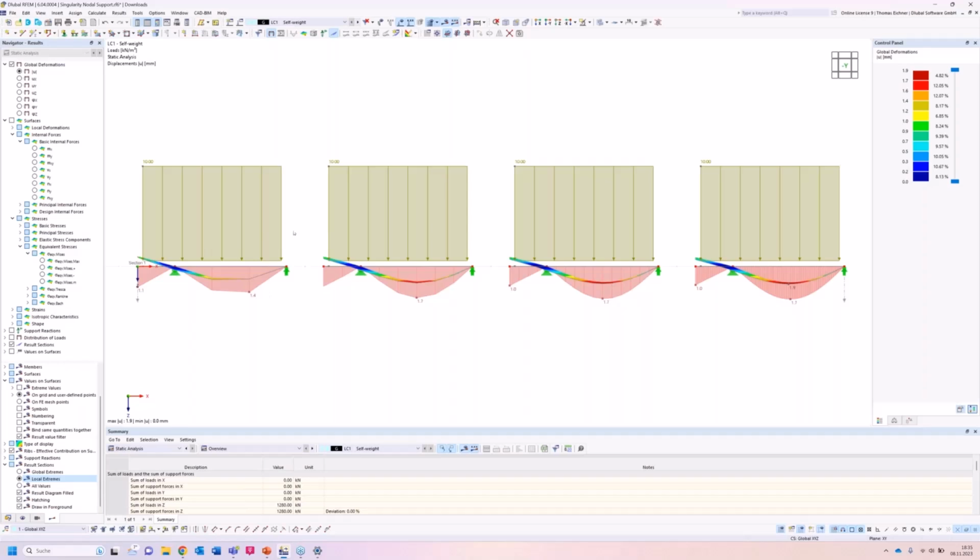So the first model was garbage all the time, because you see just one element on the left side, 3 elements here. It's just not enough, so we can ignore this. For the deformations, it seems like the singularities are not really there. So singularities do not really affect the deformations in this case.